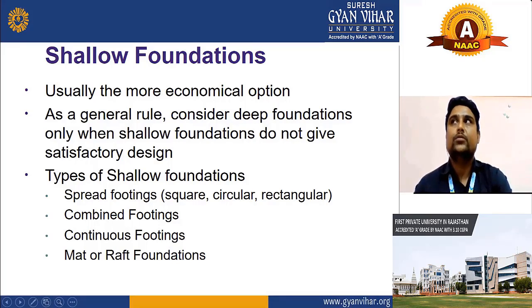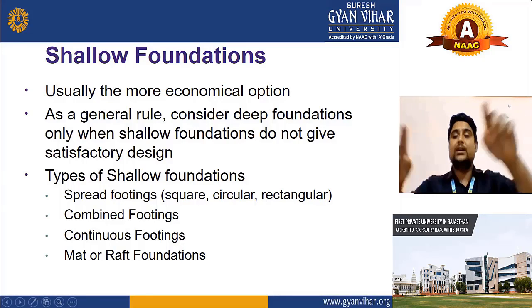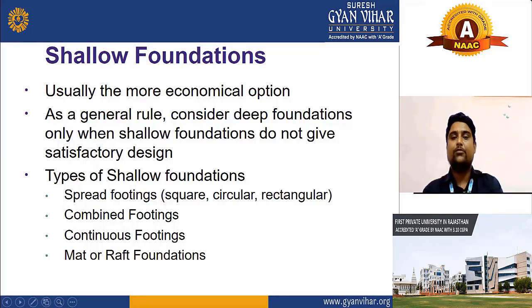Suppose we prepare the foundation for the piers of a river bridge, we have to make a coffer dam. What is the meaning of coffer dam? A coffer dam will restrain the water in that area. If you are making a shallow foundation, what will happen? The size of the area will increase, and this kind of structure is not possible in the river because you have to hold the water. In water, you cannot do construction. What you have to do is stop the water.